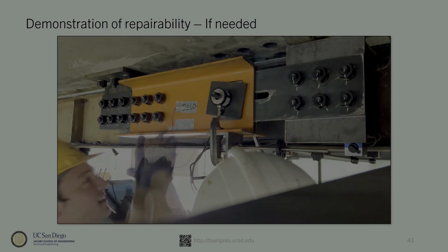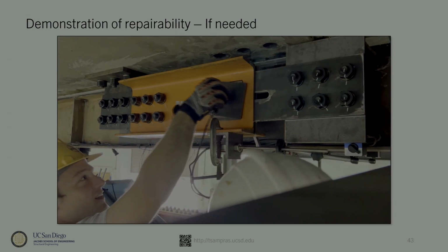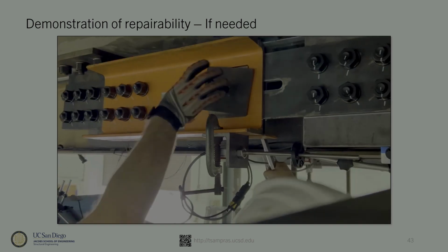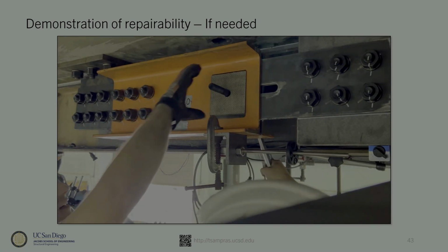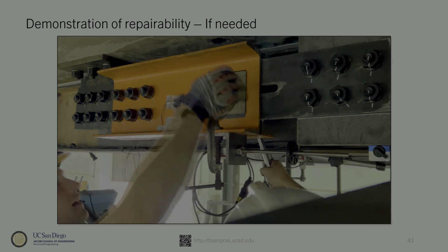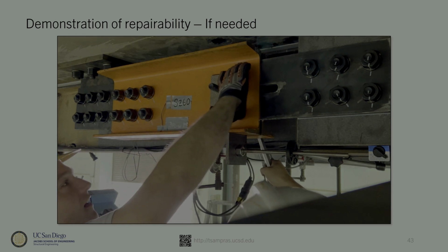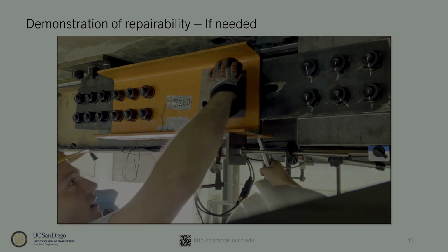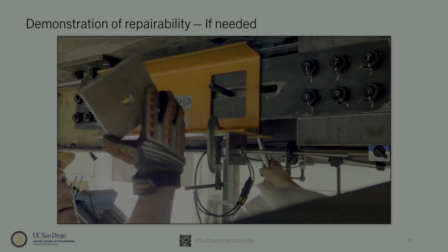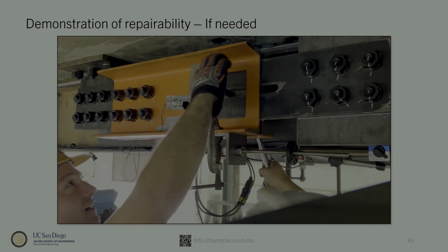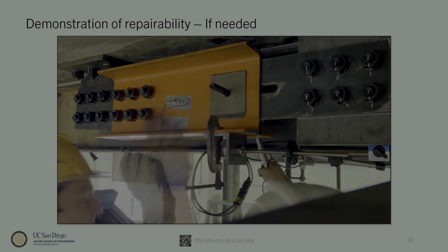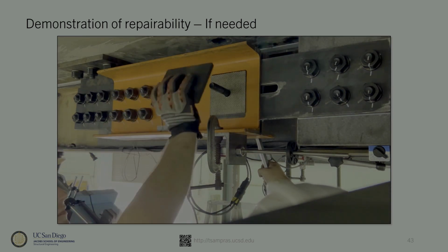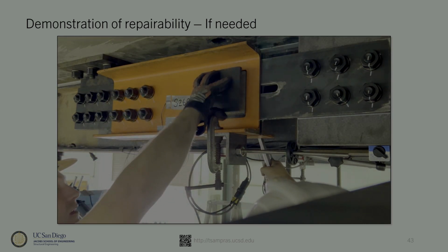Okay. So here is the visual demonstration of repairability. Just because of the design, which is the concept of putting loose plates to establish the friction interface, it allows us, after 10 earthquakes or even MCE ground motion, to go on the table, on the specimen, and in 3 minutes open up the friction interface, inspect it, and that's more of a demonstration. Make sure that the wear is as expected and put it back together and continue.